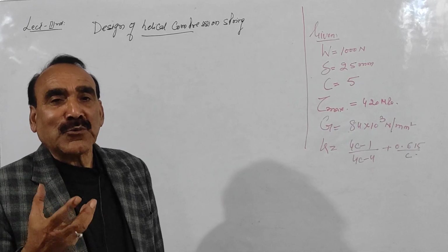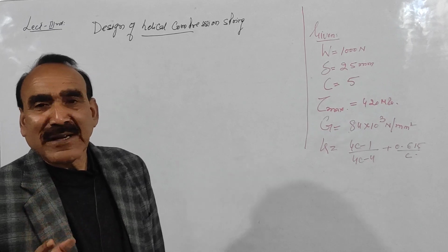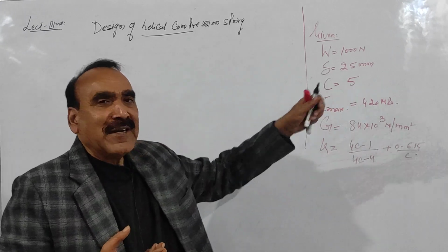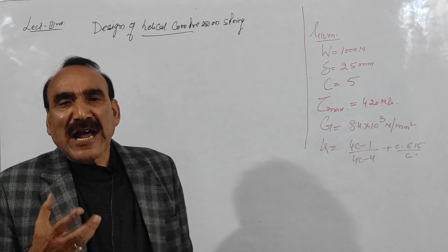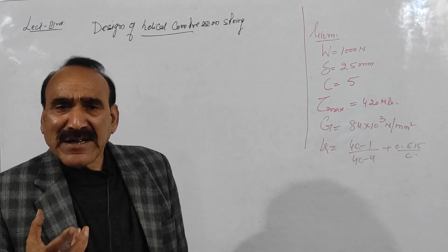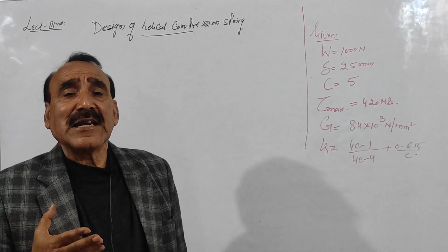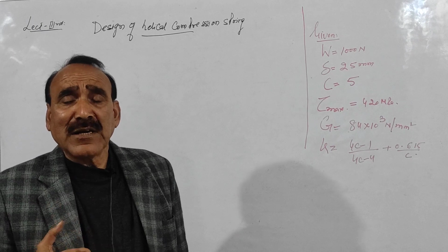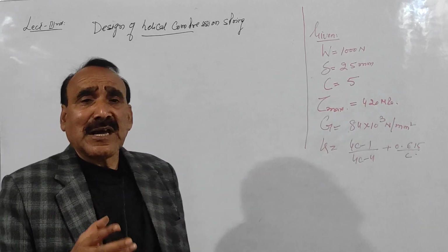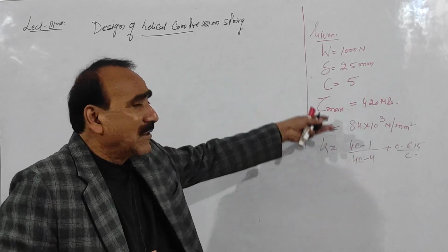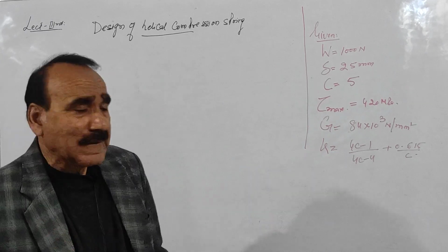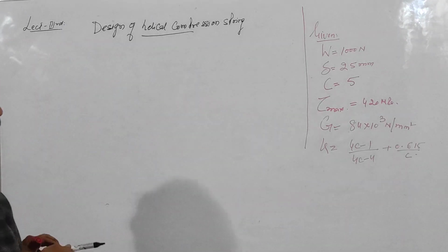जब तक आप स्प्रिंग वायर को कैलकुलेट नहीं करेंगे तो ये सारी वैल्यूज आप कैलकुलेट नहीं कर सकते, बिकॉज मीन डायमीटर आपका क्या होगा, स्प्रिंग इंडेक्स इज गिवन हियर, सो स्प्रिंग इंडेक्स मींस D upon d. तो डायमीटर ऑफ द स्प्रिंग कॉइल capital D तभी निकाल पाएंगे when you are having the value of the spring wire diameter. So first of all, हमारा जो मेन ऑब्जेक्टिव है, first we will start from calculating the diameter of the spring wire. What the parameters are given here, by using these parameters we will just think over that how we will calculate that, right? So start करें इसको, प्रॉब्लम को।